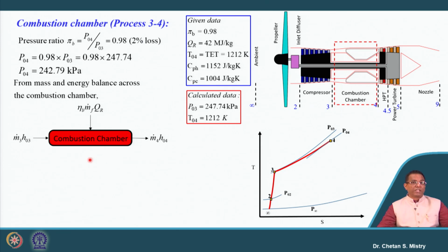So in this case, if we write our energy balance equation, that is what we have done repeatedly for a number of cycles, all the cycles we have discussed. Let it be a turbojet engine, a turbofan engine, where we have discussed all 8 kinds of configuration, or a turboprop engine. So this formulation will remain the same.